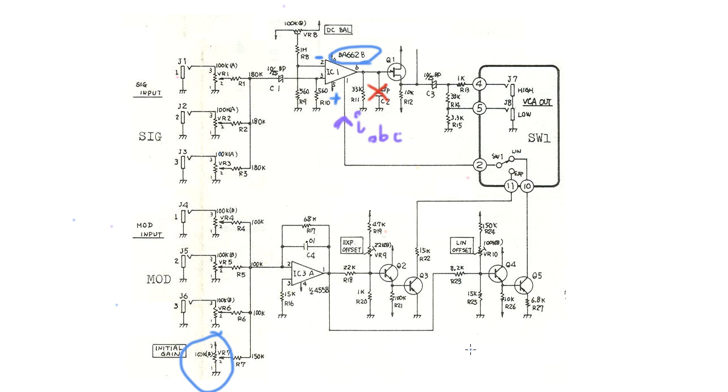We would have to analyze this in a lot more detail to figure out whether my hypothesis is right or not. I should note that most OTAs suggest that a good practical maximum for the input current is something like 1 milliamp. If you start pushing it beyond that, then you're into iffy territory, and you might fry your OTA. But that maximum will vary from OTA to OTA. You'll want to check the datasheet.